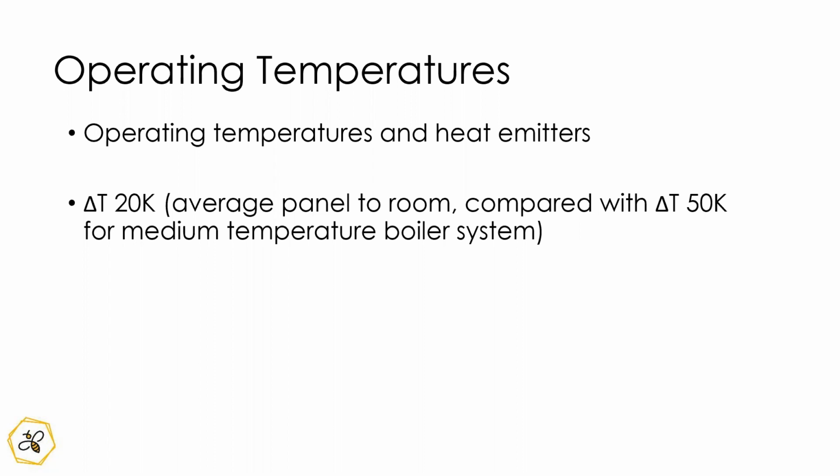So it's more like a 50 degree delta T, whereas with your heat pumps, you'll be using sort of 35, 40 degree water. So that's just a 20 degree delta T with your room.